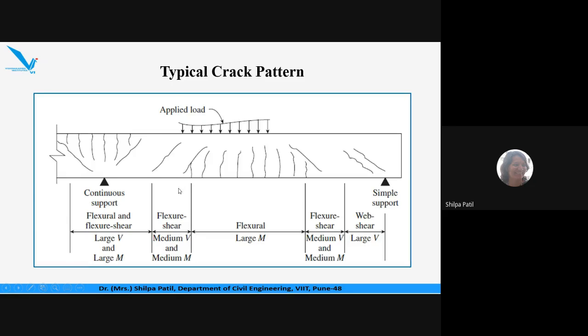See, there is shear in this region also, along with moment. In this region, at the center the shear force is exactly 0, but as we move away from the center, the effect of shear force will be there. So whatever concrete is present in the beam, and whatever main reinforcement is present in the beam, they also take care of that additional shear force along with the flexural or bending stresses.